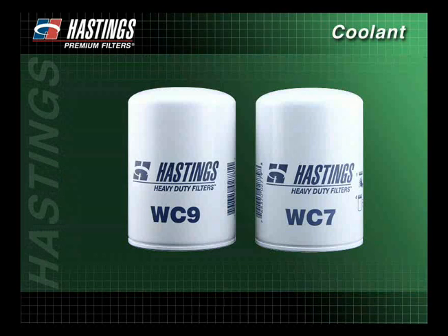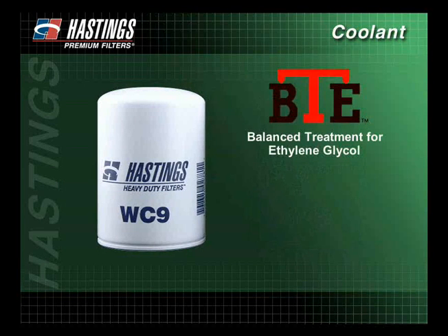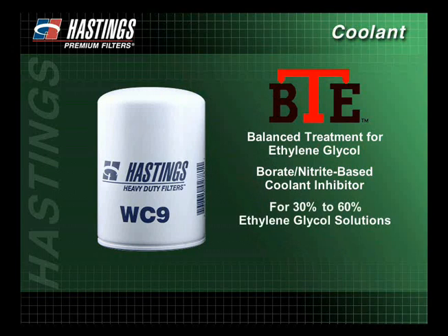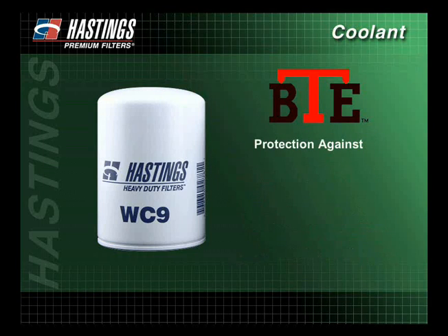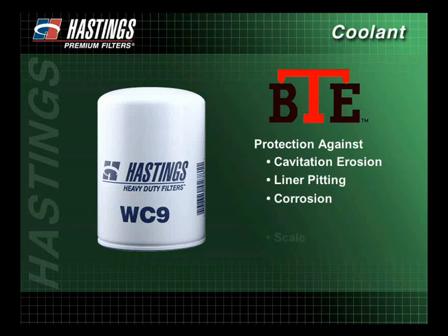Hastings offers coolant filters with two types of SCAs. BTE, or Balanced Treatment for Ethylene Glycol, is a borate nitrite-based inhibitor designed specifically for 30 to 60% ethylene glycol solutions. BTE is also compatible with 30 to 60% propylene glycol solutions. BTE provides superior protection against cavitation erosion, liner pitting, corrosion, scale, and foaming.